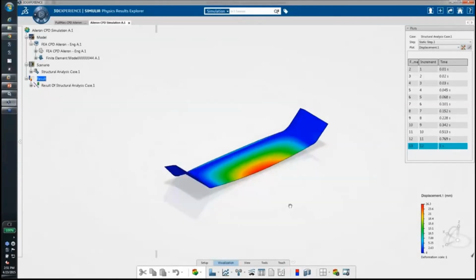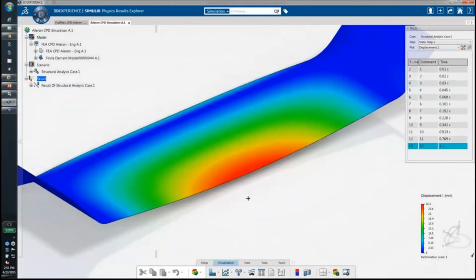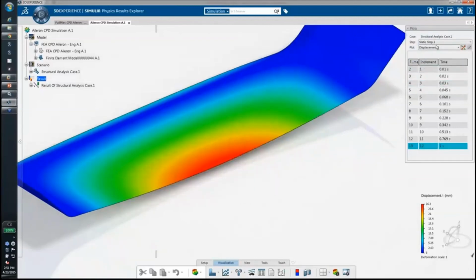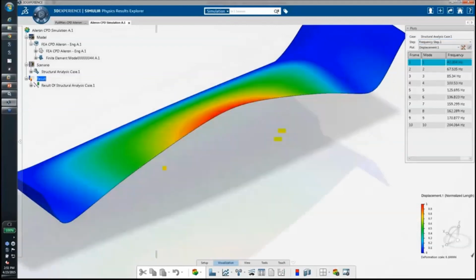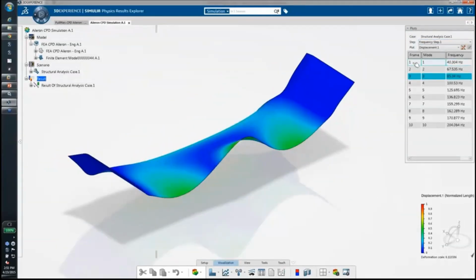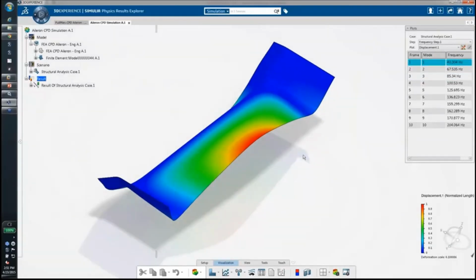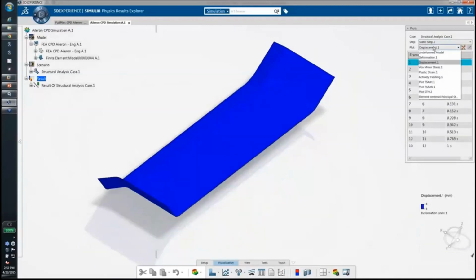But I do have a displacement plot showing me the amount of displacement, and then I also can plot out. In this case, I did some frequency modes, so I extracted the different frequency mode shapes. It's exaggerated, but I can see if there's some distortion maybe in drop-off areas and where it could cause some delamination. We'll go back to the static, and we'll go in and just take a quick look at the Tsai-Hill.